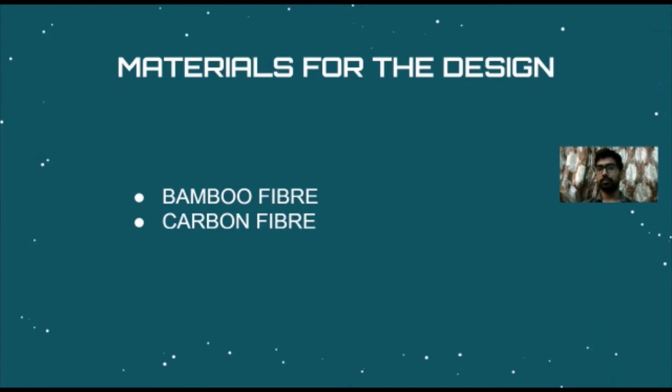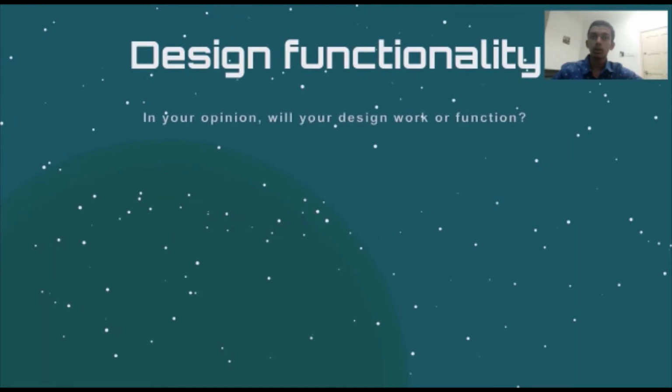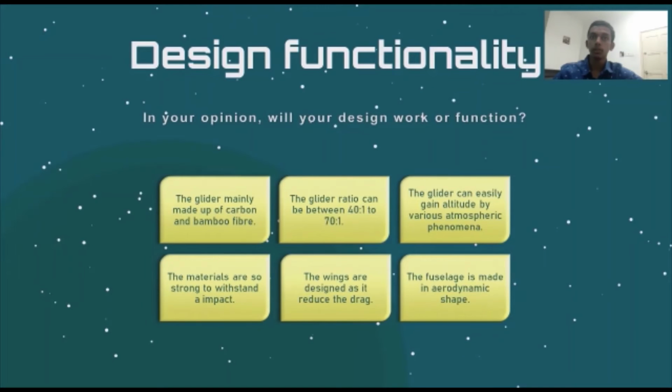Thank you very much. Now it's about design functionality. Our glider is mainly made up of bamboo fiber and carbon fiber. These are lightweight materials and the weight is distributed at strategic points in an efficient manner. Next, the gliding ratio for this glider can be between 40:1 to 70:1, which means the glider can fly for 40 to 70 kilometers if it starts flying from 1 kilometer high.